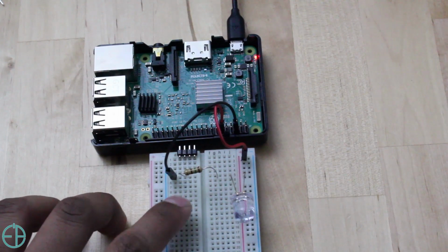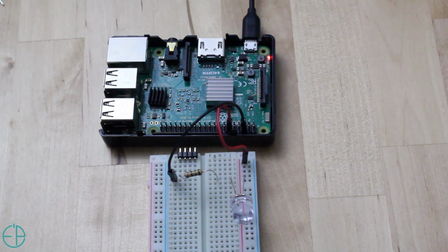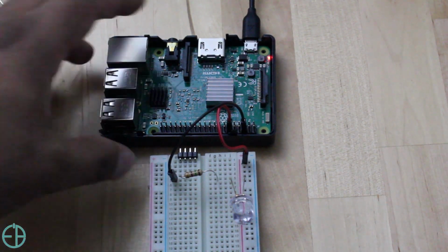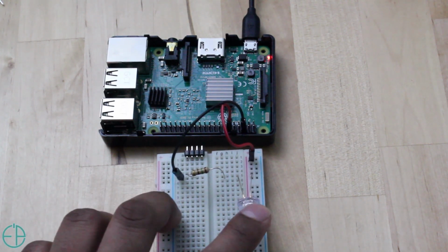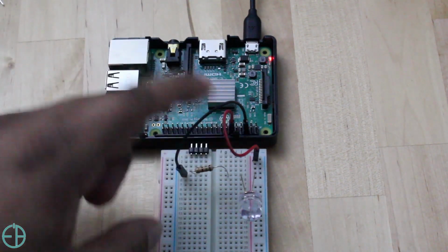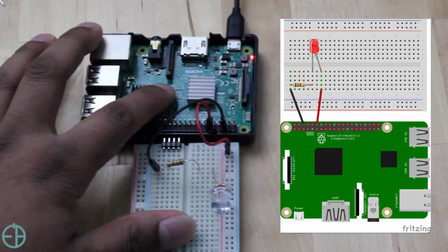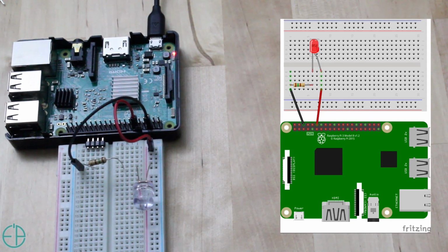So this setup is pretty simple. Right now I'm using Raspberry Pi 3. This setup can be done with any Raspberry Pi, including the 0 and the 0W. And I have a regular dome red LED here. This is a big one, 10 millimeter instead of the regular 5 millimeter. The power is connected to pin 18, and the ground is connected to ground, taken through a 150 ohm resistor. You can use this with any LED you want with the proper resistance.